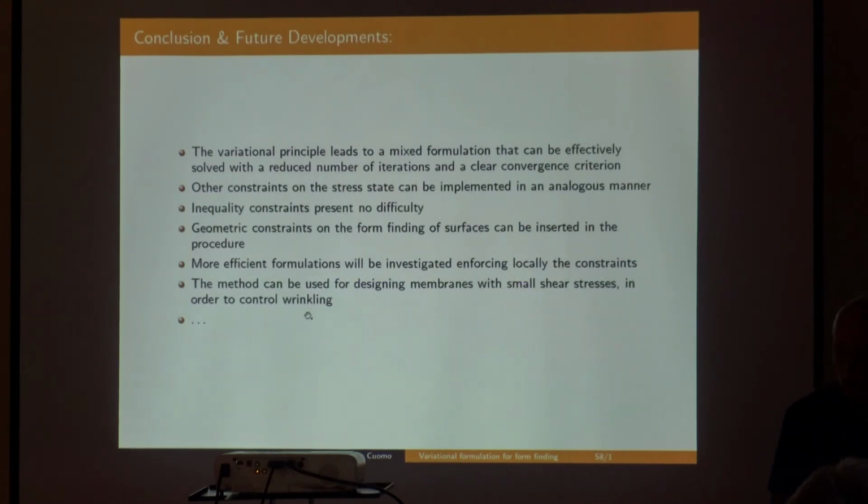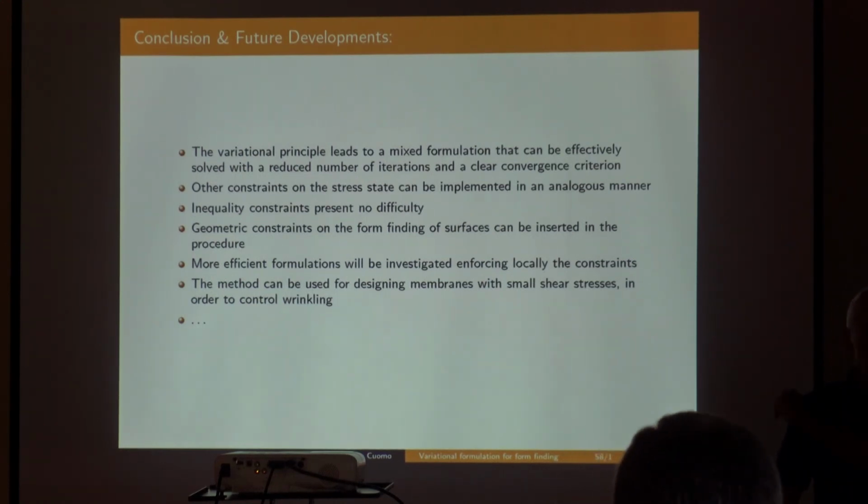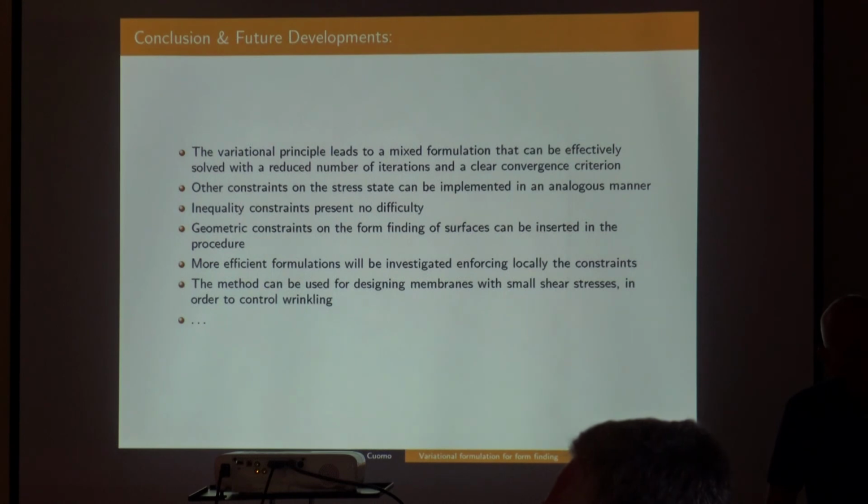Okay. Conclusions. The mixed formulation can be effectively solved with very few iterations, we find the solution. And then we have a clear convergence criterion. I've shown the case of a minimal surface, which is the most common, but you can enforce other constraints on the stress state. The formulation is a Lagrangian, so you can introduce any kind of constraint you need. Even an inequality constraint. We have not done that yet, but you can enforce inequality constraints.